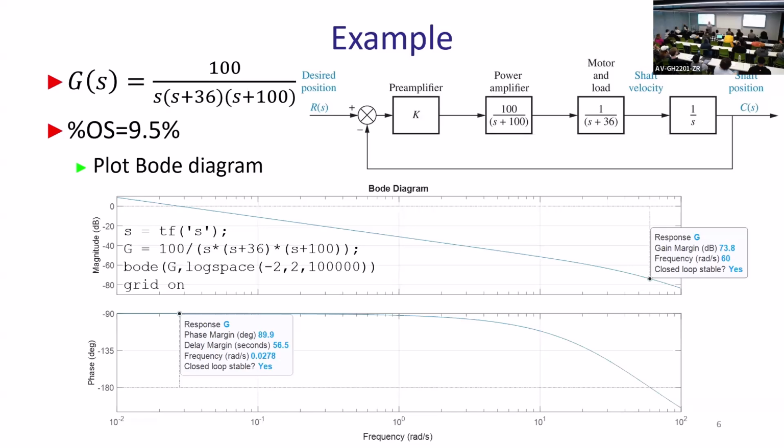So this is how far away your Nyquist plot is when you rotate it. This is phase margin, or how far you can scale that Nyquist plot to cross the margin of stability. So phase margin means how much you can rotate the Nyquist plot until you lose stability, and gain margin means how much you can scale, inflate, the Nyquist plot until you lose stability.